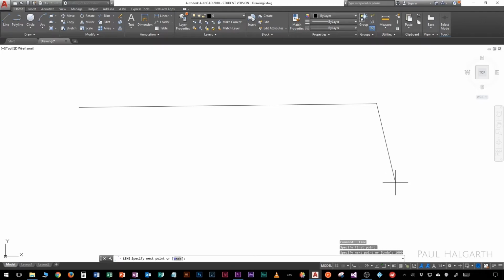Now AutoCAD doesn't know that it's millimeters, it doesn't care what the units are, it just knows that it's 1000 units. In my head it's in millimeters, because everything we draw in our industry should be in millimeters. And we draw everything at a scale of 1 to 1. So if it's 1000 millimeters in reality, then we draw it 1000 millimeters on our screen.